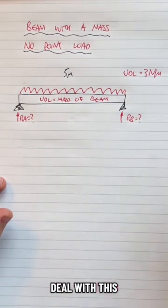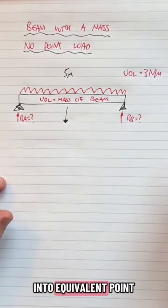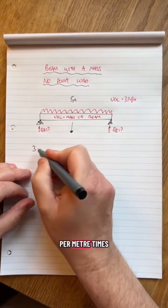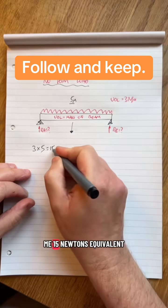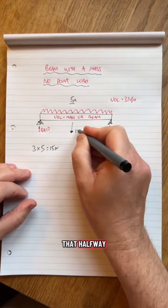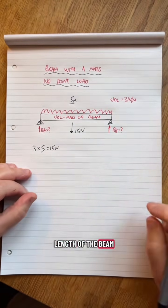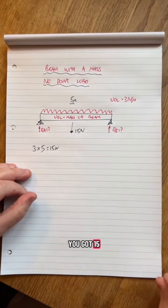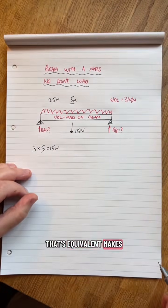The way you deal with this is, I'm going to convert the UDL into an equivalent point load. So I'm going to do 3 newtons per meter times 5, because there's 5 meters. That gives me 15 newtons equivalent. And what you do is you put that halfway, because the UDL acts across the entire length of the beam. So you put it halfway of where the UDL acts. You've got 15 and it's 2.5 meters in. That's equivalent. Makes it easy for us.